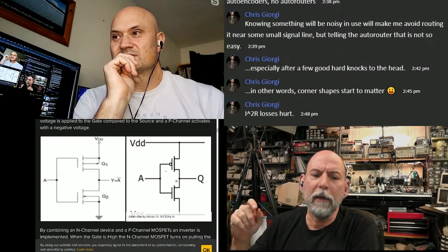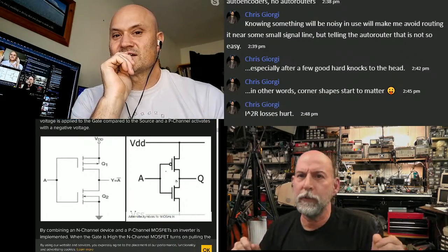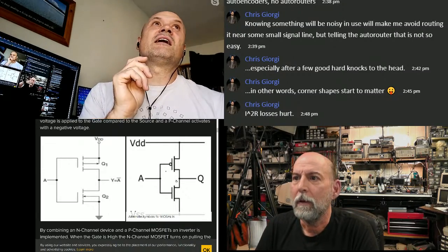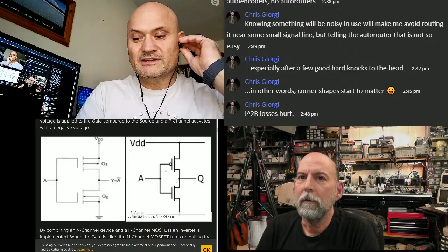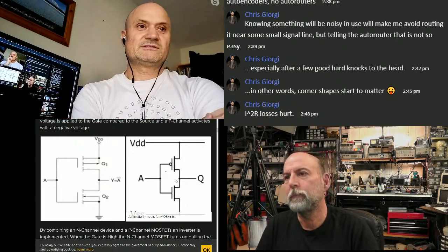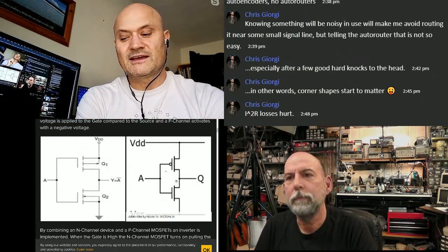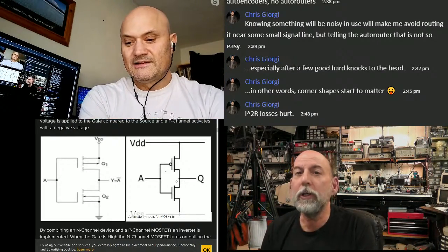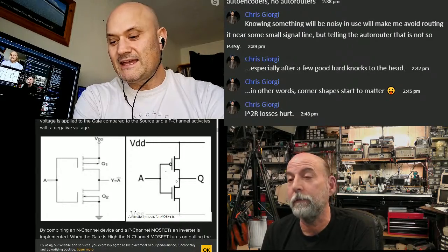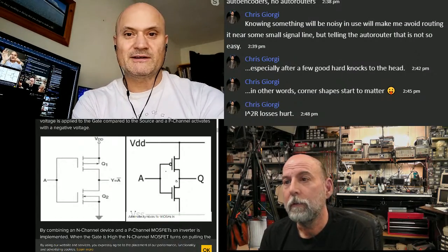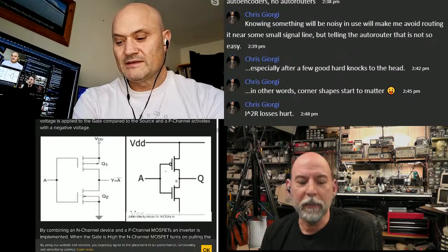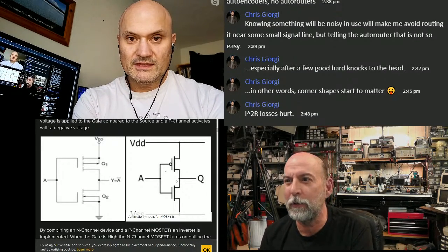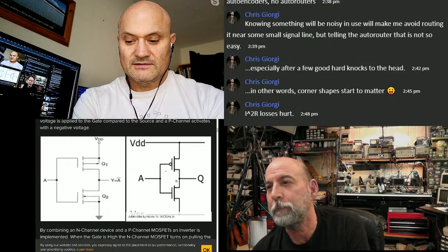So, have you ever designed with board stabilizers? Have you ever used them, or I'm sure you've consulted on them? I personally have not done a PCB design that uses stabilizers. By stabilizers, you mean the extra mechanical part you solder to the board? Yeah, which can also carry that 80 amps. You can use it as a bus bar. We're used to seeing that on older stuff, but I think they're making a resurgence a little bit as the speeds go up.